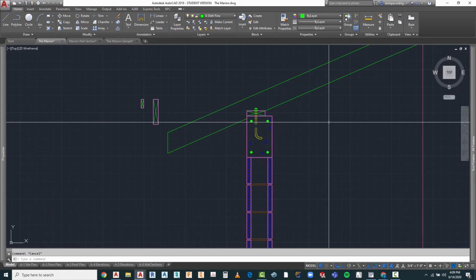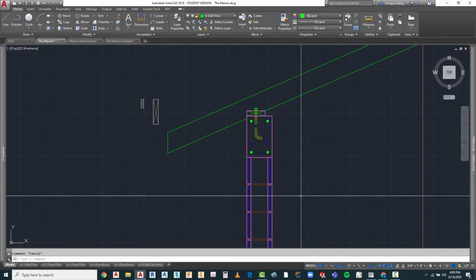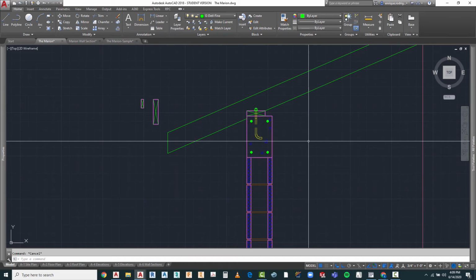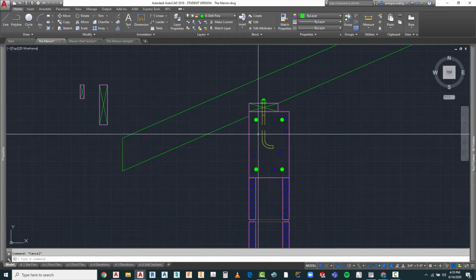So 2 feet, 18 inches, 48 inches, 12 inches, they're all multiples of 4, or 4 is divisible by those numbers. Again, you look at drywall, you look at plywood. Plywood is 4 foot by 8 feet. So what this provides is, if you have the structural members that you're going to screw the plywood sheathing to, you want to make sure that you have an edge condition that's going to be screwed into it. So it's very, very important to maintain those dimensions so that you have the ability to hold down the structure and have those elements be tied together.